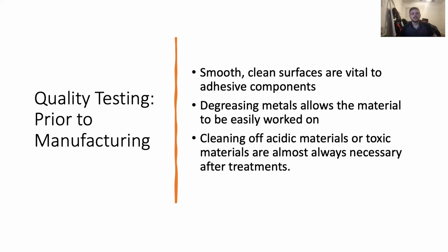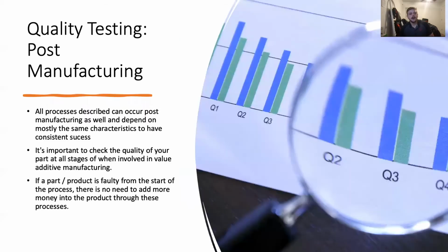So it's just showing that quality testing is necessary in between manufacturing processes, post or prior to these enhancement processes, to be sure it doesn't ruin the manufacturing process later down the line. And then basically the same thing for post-manufacturing. For example, after manufacturing many pieces of aluminum siding for your house, you have an automated system to paint these metals. If the metals are bent or torn or sheared from the manufacturing process, the application of paint may be uneven or even ineffective.